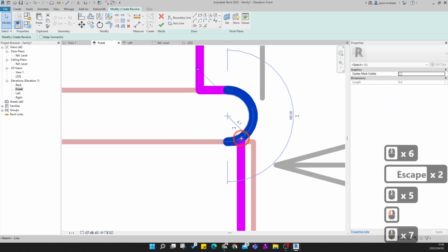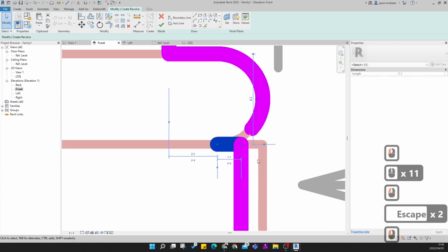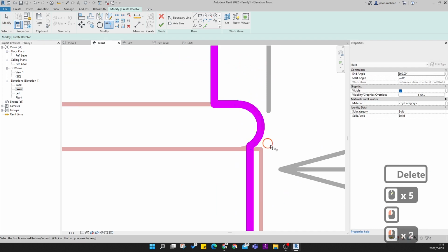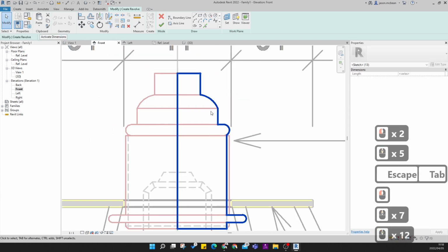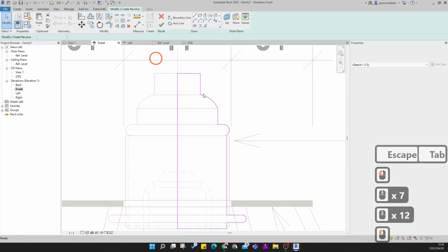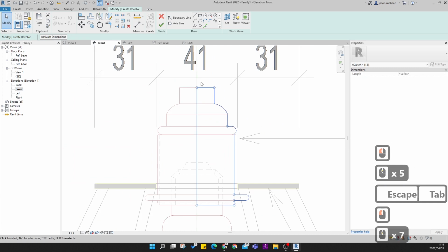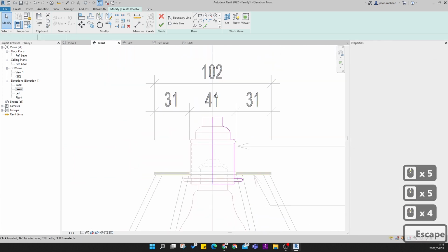Okay, so this is a bit tight, so what I'm going to do is move this back to there. I'm going to get rid of that bit of line work, and I'm just going to use a trim tool. I want to trim these objects together, and now if I press tab, they should all be open, and you can switch off your line weights over here just to make sure. They all need to be open hollow nodes. If there's a solid node, it won't revolve.